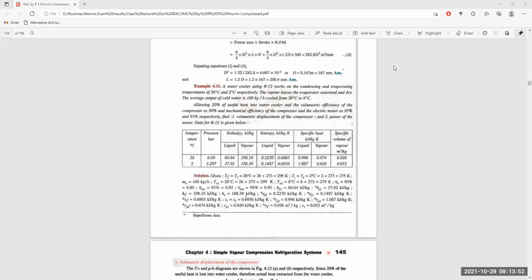We send this liquid refrigerant at high temperature and pressure to an expander or throttling device, which cools it to a lower temperature, and the volume is expanded. Thus, pressure is reduced to the lower pressure of the system, and this process finishes at stage 4, which is the inlet of the evaporator.